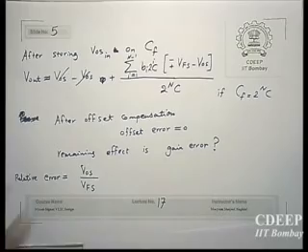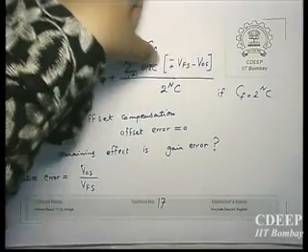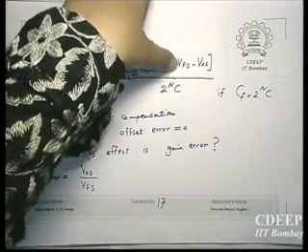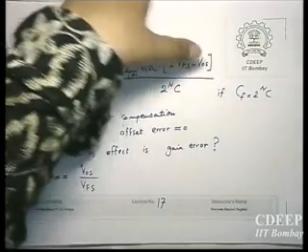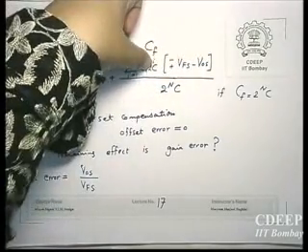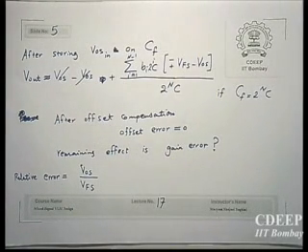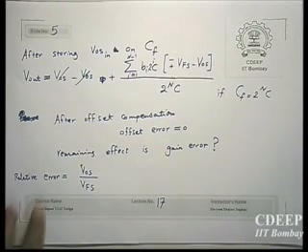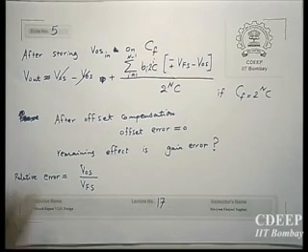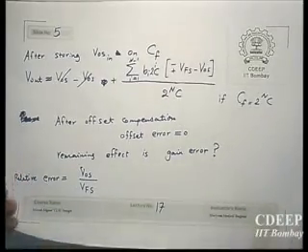What I did is just factor out V full scale, and therefore you will have 1 minus V offset upon V full scale. This coefficient also is common for both, therefore the relative error eventually is V offset upon V full scale. Relative error means the amount of error you get with respect to the amount of voltage you wanted. So it is constant, but still we can prove it is really gain error only.